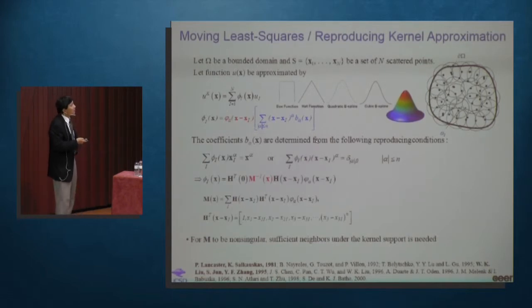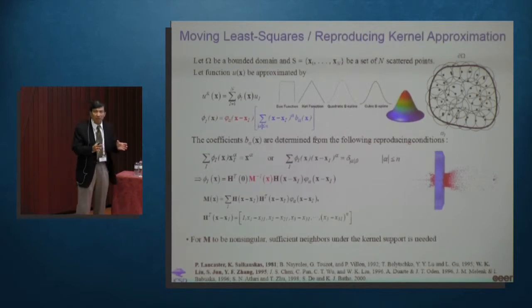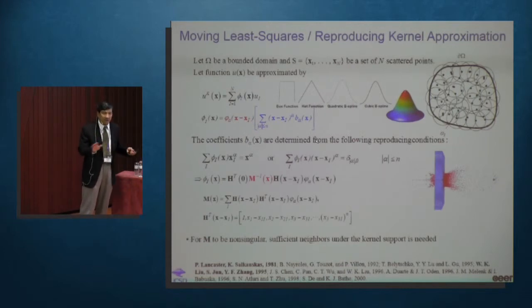Well, this is not a major problem when you are solving a continuum problem, because you know the deformation. You can use your deformation gradient to map back to the undeformed configuration. So if you know how many neighborhood particles you have to cover, you can set the condition at the beginning, and then you use the deformation gradient to check the neighbors, and everything is fine.